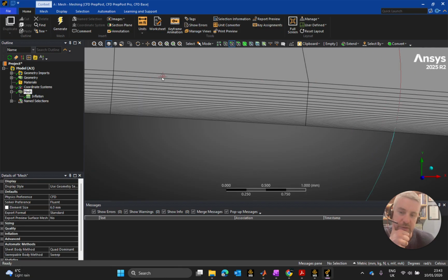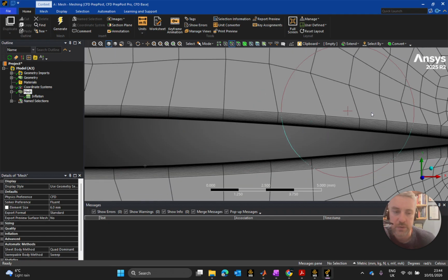Of course, there's different velocities over that height, but they should be thin enough that the velocity difference between the centroid of that cell and the one below it isn't going to vary an awful lot linearly. Down here, they vary an awful lot linearly, but that's why they're so tight down there, as our velocity moves up towards the free stream. So we're going to have a nice built velocity profile there. That'll give us an unstructured mesh.